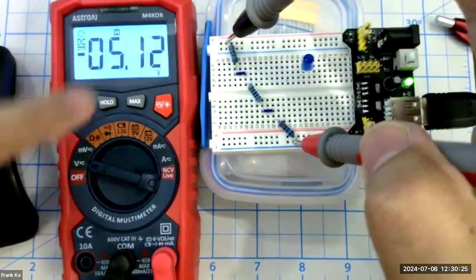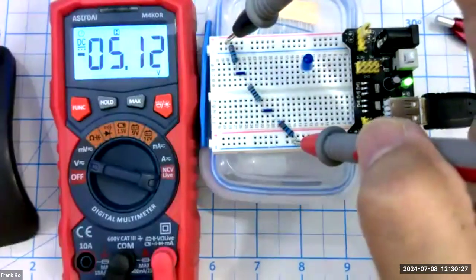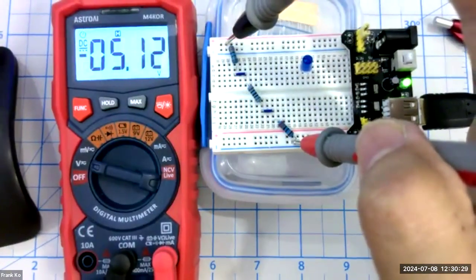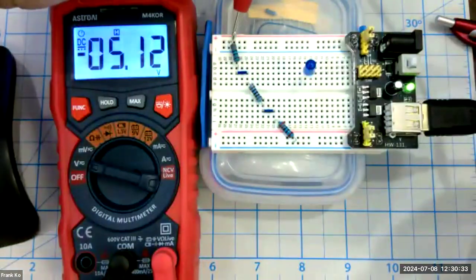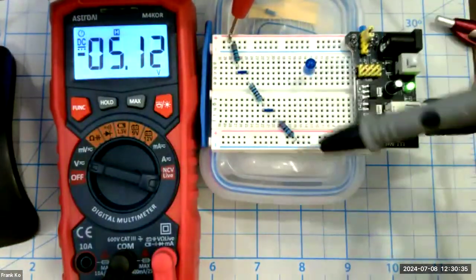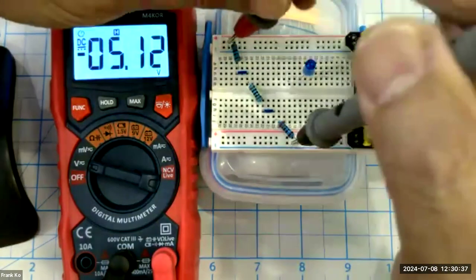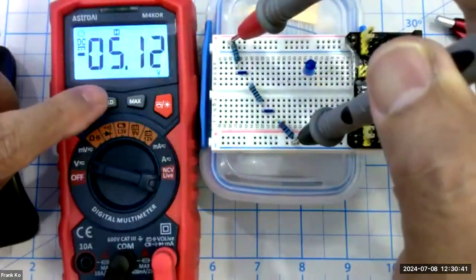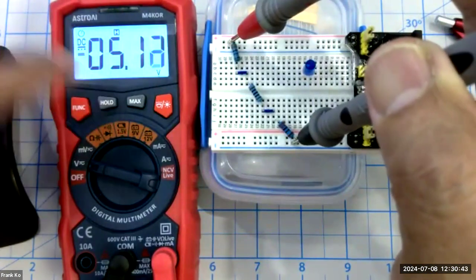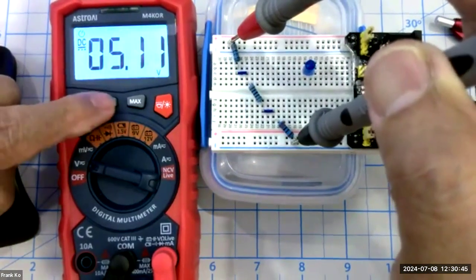All that tells you is to be mindful of what color probe needs to go on what part of your circuit. So the red colored probe needs to be on the more positive side of the circuit. The black colored probe needs to be on the more negative side of the circuit. I'm going to hold this in place with one hand, and with the other hand, release the hold, and the negative sign will go away. Ta-da! Negative sign went away.